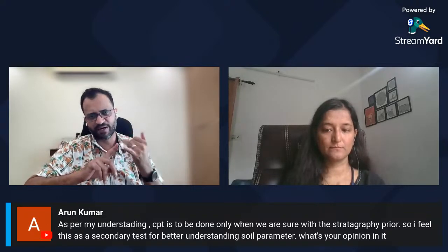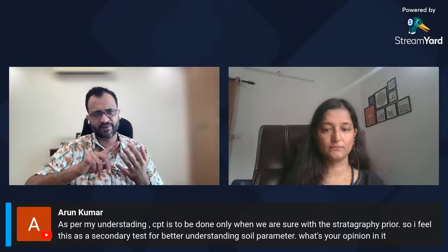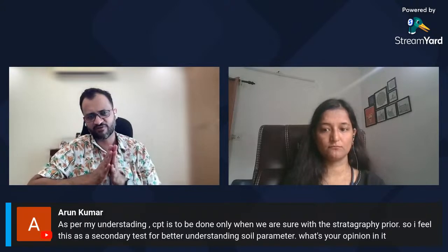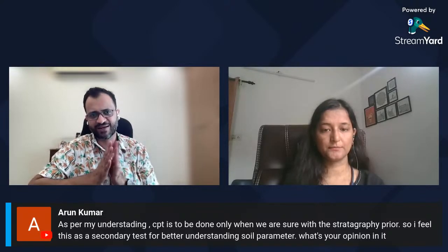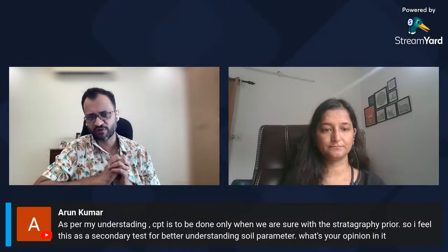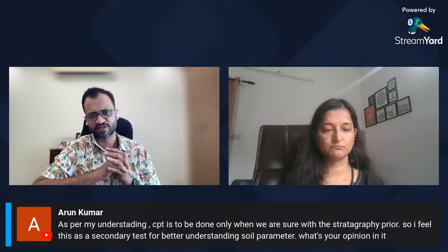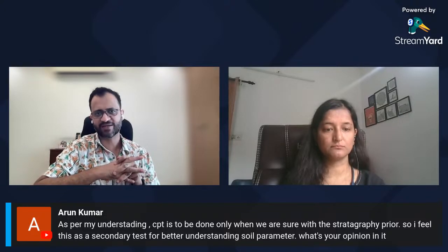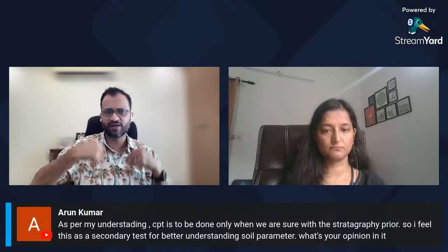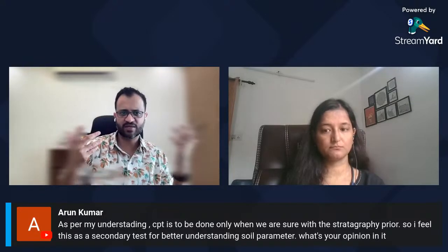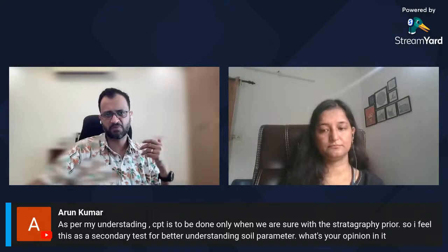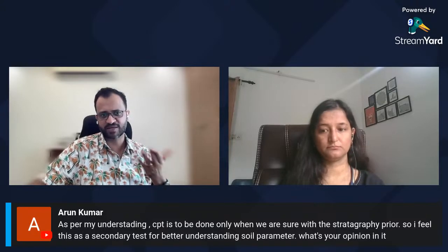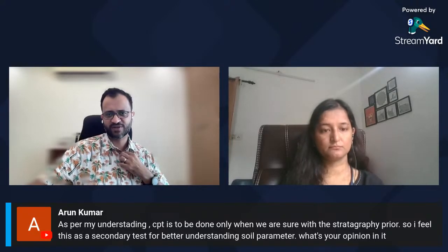It could be pre-bid, pre-purchase, preliminary, whatever. If you're doing the first cut investigation very quickly, I would like to go with CPTs because you can do a bunch of CPTs very quickly and get a very quick ground profile across your site, and then you can design your detailed investigation based on those results. So I like CPTs as a phase one choice of investigation too.